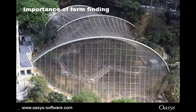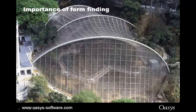Another important thing, doing something like this where you have the cable nets supporting the arches and the arches supporting the cable nets. Those arches are quite slender. If the forces get out of balance on those arches, the arches will buckle. Excuse me. Form finding helps you to find the balanced structures.